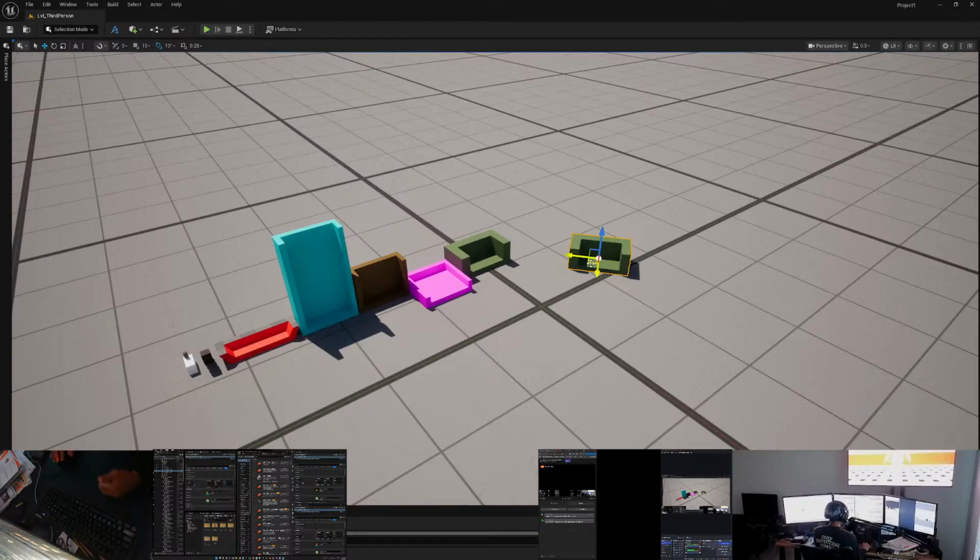For me, I personally like to combine my walls, floors, and ceilings as one large mesh, one solid mesh. And then I'll cut out or do some sort of Boolean to expose the openings for doors and windows. I don't do thin sheetrock. I don't do 2x4 studs. I don't do the insulation part of the wall. I do from the outer sheetrock to the outer sheetrock of any rooms that are facing each other. And I create that as one solid block attached to floors and walls.